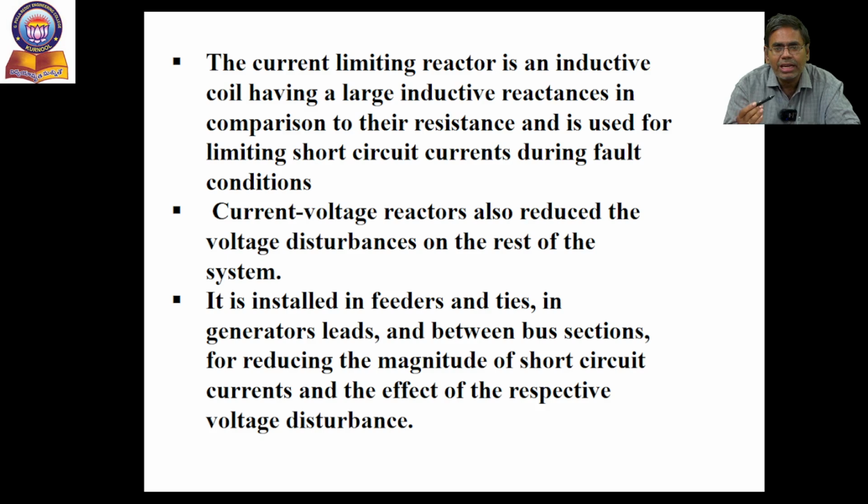When a reactor is connected in series with each generator, that is nothing but a generator reactor. A reactor connected in each feeder is a feeder reactor, and a reactor connected in series with the busbar is a busbar reactor. Busbars are connected in two types: one is the ring system, and the other is the tie bar system.